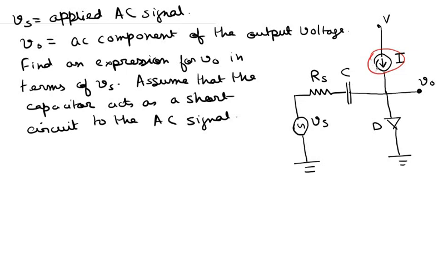So this is basically not like a resistor. For a resistor, the current is proportional to the voltage, or for a capacitor, the current depends on the temporal differentiation of the applied voltage. An independent current source, on the other hand, basically means that irrespective of the voltage drop across the current source, it would conduct a constant amount of current.